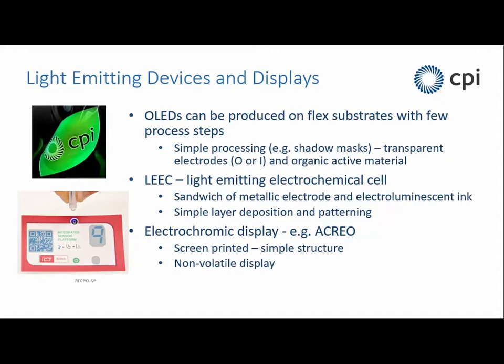One of the challenges with OLEDs is encapsulation, because any moisture that gets near these materials will cause them to deteriorate very rapidly, in fact. So encapsulation is critical. But other forms of display like LEEC, a different electrochemical arrangement, and electrochromic at the bottom, is a very useful approach to creating displays on devices that are relatively simple. We wouldn't consider at this stage the idea of creating a high-resolution display with OLED.